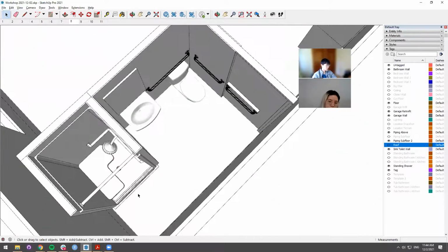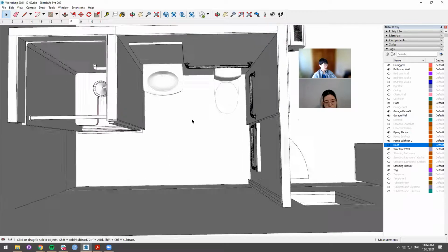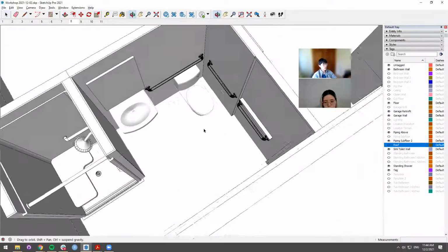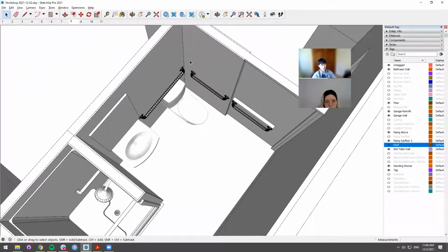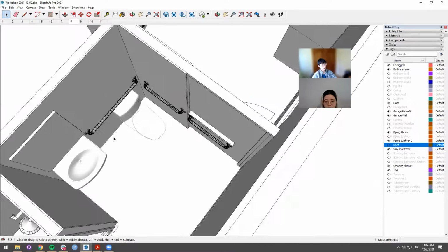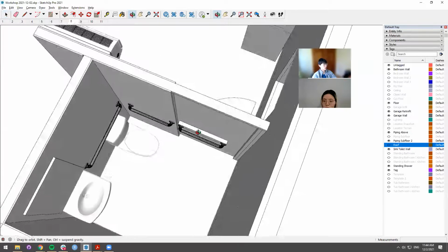So this has clearances for the shower. It's got T-turning ability in this main space. And then the ADA bathroom requires a certain length of rear bar, and then that 54 inches of side bar. And so what I've mocked up right now, as you can see, this is certainly hacky unless we make this look good, is a level additional, say 3 foot or 2 foot grab bar with a little bit of separation here. So that door swings outwards.